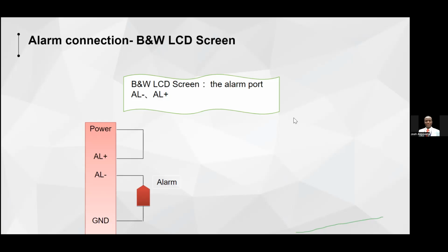That is what that break glass accessory is for, and it is meant to be connected to your standalone or your control panel, depending on the method of communication configuration you adopt. So that break glass accessory is meant to connect to the break glass relay in your device. So in the event of fire, you see the break glass clearly marked and installed close to the door. You hit it and it de-energizes your lock and keeps the door open in the event of fire. Does that answer your question, Mr. Godwin?